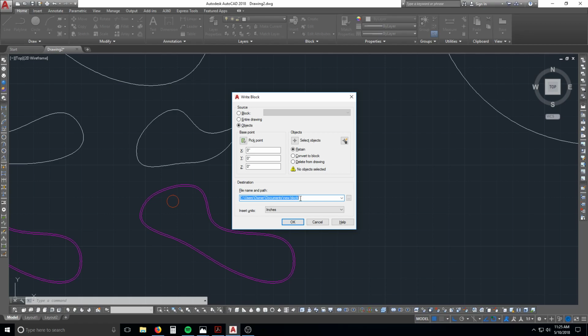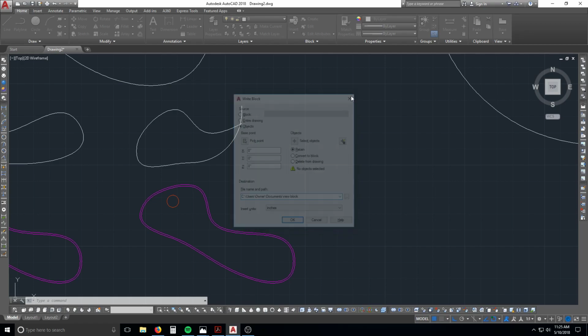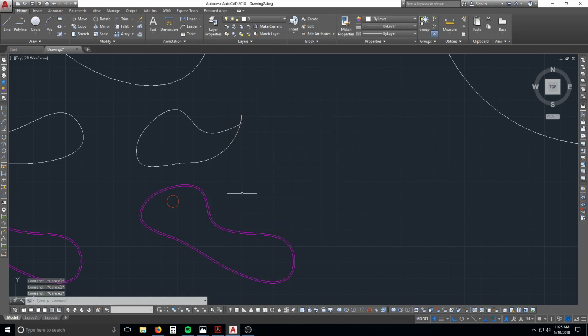I used to use it a lot, not so much anymore, but at any rate, what we're going to do here, the other way to get a block in without confusing you, if I haven't already, is if you highlight your object like there, and if you Control X, I didn't grab that one, but that's okay. Now if you Control Shift V, Control Shift V inserts your copied object as a block.